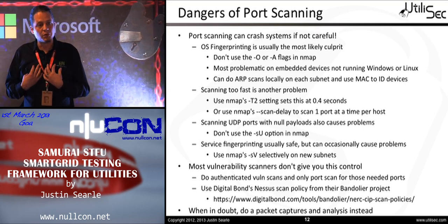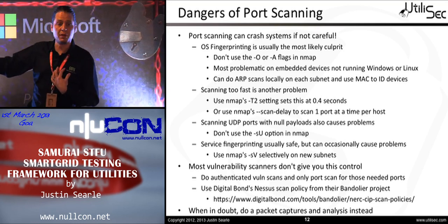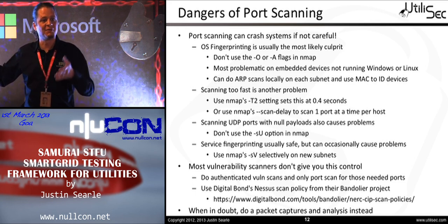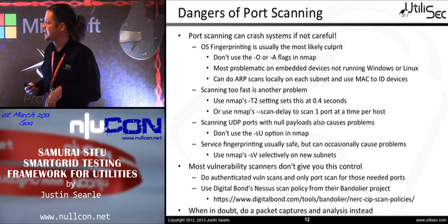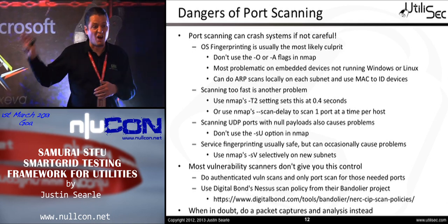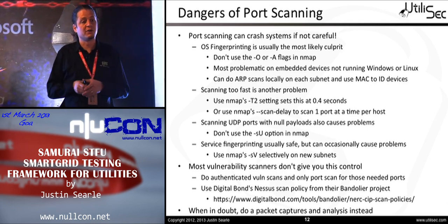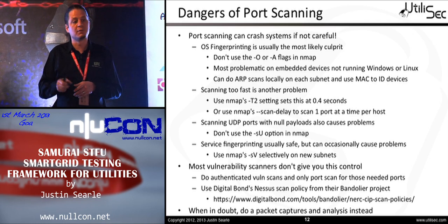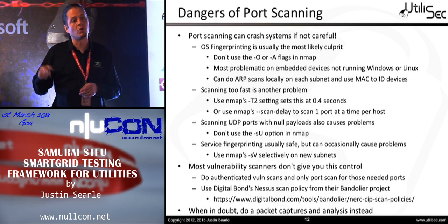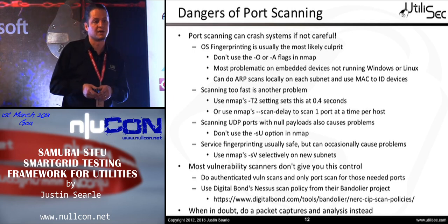In the IT world, we see this as a great capability doing authenticated scans, but we always see it as kind of half the picture. Well, what happens if there's more vulnerabilities you can't see authenticated? Okay, it gives us more information authenticated. But inside of the control center world, running unauthenticated scans and doing all the different checks is a sure way to be able to crash multiple systems inside of the infrastructure. And sometimes not just crash, but permanently brick, requiring being sent back to the vendor themselves.